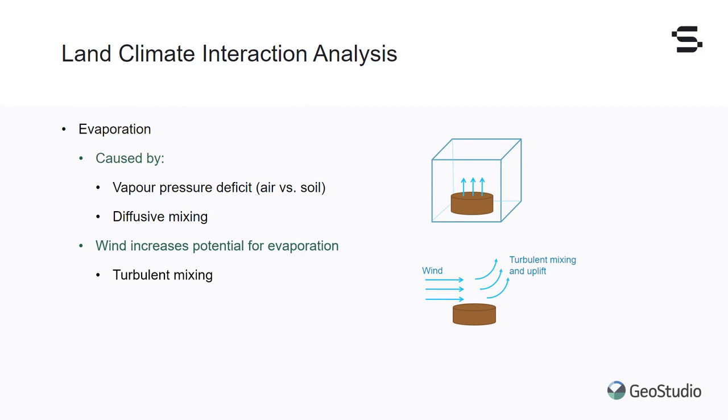In reality, soil is exposed to atmospheric conditions, which also influence evaporation. Wind generally increases evaporation potential, as wind blowing across a surface creates turbulence and enhances vertical mixing of air that carries latent heat, or water vapor, and sensible heat upwards. Vegetation may decrease evaporation by increasing surface friction, which limits wind effects, and by providing shade, which decreases the energy inputted from the sun that contributes to evaporation. Thus, potential evaporation may be dependent on the moisture content and diffusive mixing in the soil, incoming energy, wind speed, and the vegetation soil cover fraction.